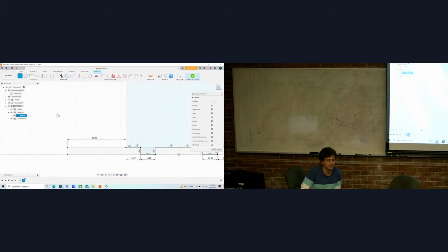Okay, this I'll show you. One other thing about dimensioning, you don't need to follow what I'm doing. But let's say I have this line here, and for whatever reason, I know that this needs to be 17 times 3 millimeters. Instead of getting out a calculator and doing that separately, you can just type in 17 star 3 and press enter, and there you go. You have the full dimension. And again, if you edit that, it has originally been typed in. I mean, it adds parentheses and millimeters to it, but it is originally the thing you typed in. It doesn't convert the number. Especially when you have more complicated geometries that require math like that, it's just something useful to know. You don't need to do the math externally, just type it in and it will calculate it for you.